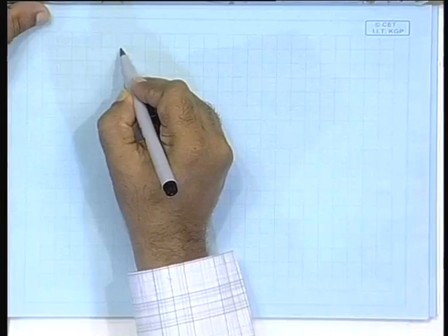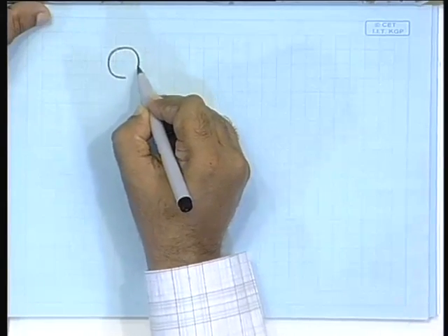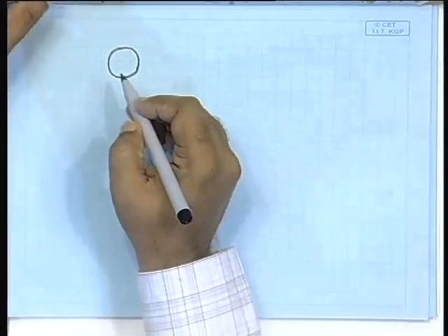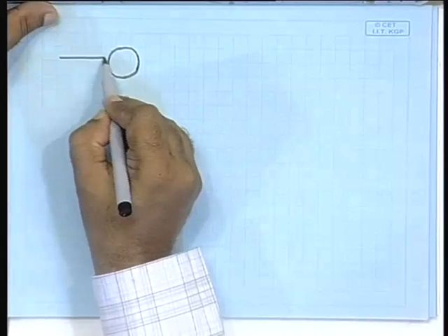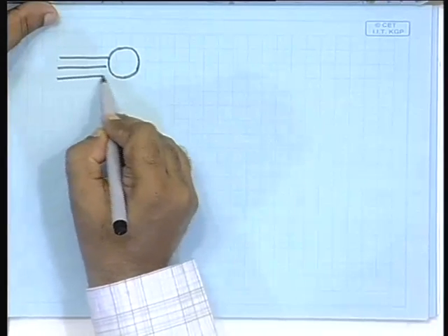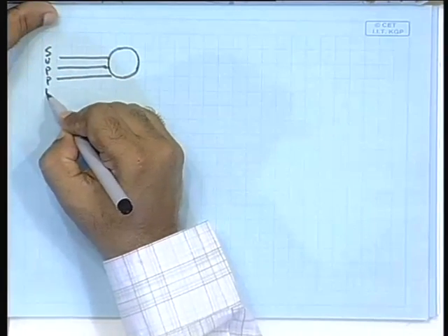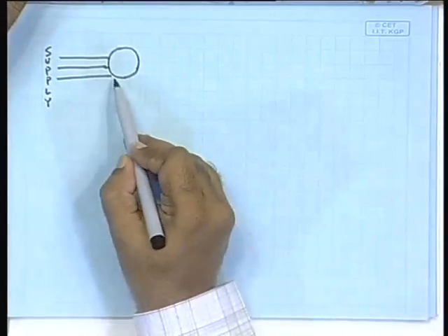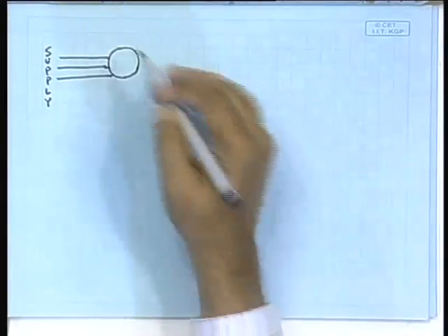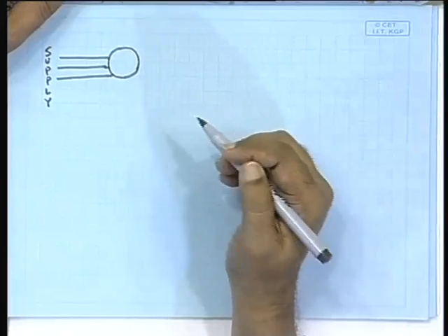Now, in that case, if you have the arrangement somewhat like this, then the process of build up of the voltage, which I stopped with in the last class, can be obtained conceptually as follows: supposing you have taken the machine separately, say the machine here, I am drawing the machine schematically, just as a circle, and you have supplied it from a 3-phase source with the supply side here, as a motor, not as a generator, and run it free in the no load condition.